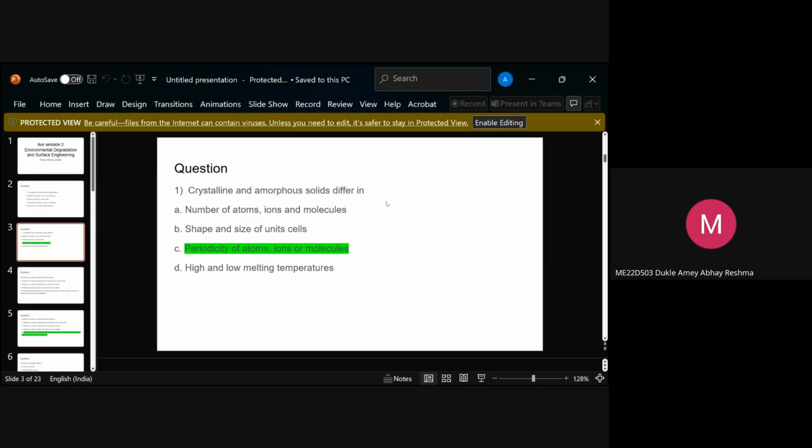So, what is the crystal structure? Crystal structure corresponds to the placements of atoms and molecules in the entire material per se. So, in a crystalline structure, the crystal structure is very different. It will be like FCC, BCC, HCP, likewise. But in an amorphous structure, the crystal structure is not well defined. It can be all over the place.